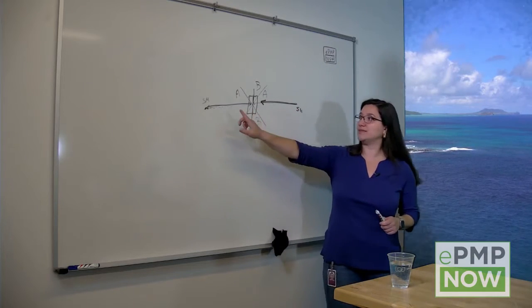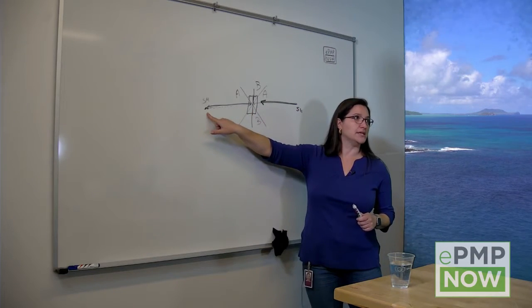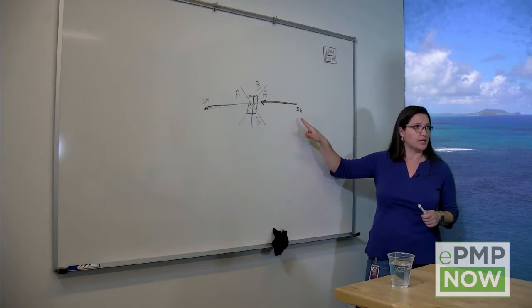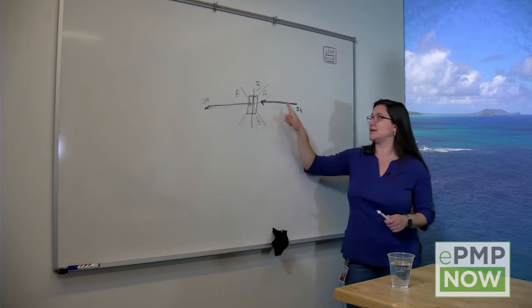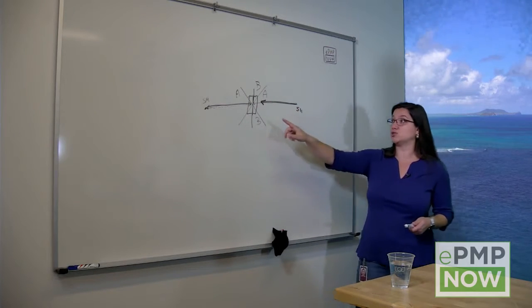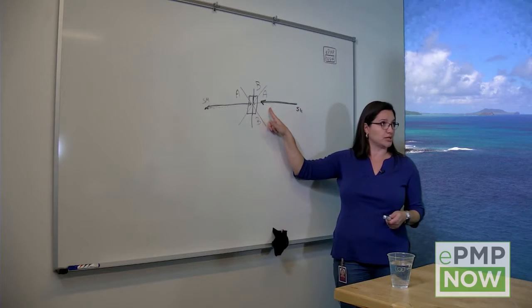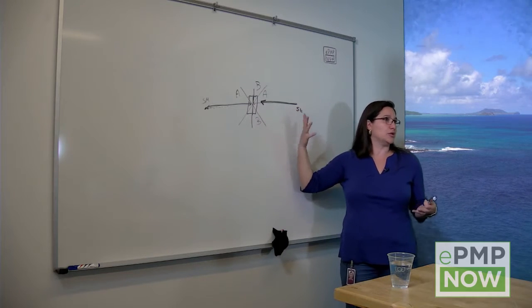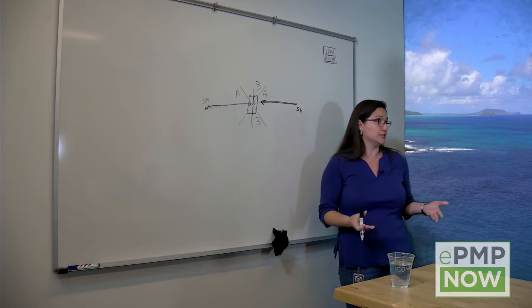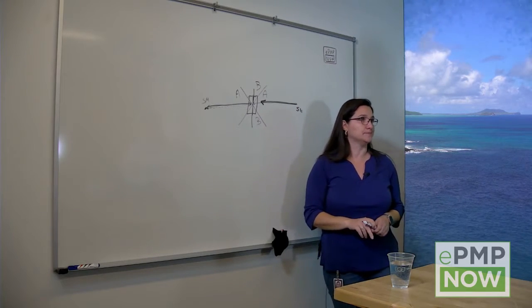So when this SM is scheduled to transmit, it will not always transmit at the same time as this specific SM. So sometimes it will talk at the same time as an SM that's farther out, but sometimes it will be scheduled at the same time as an SM that's closer in. So the 2 schedulers are independent, which means, again, the front to back ratio is very important to protect the signal. Great, thank you very much.